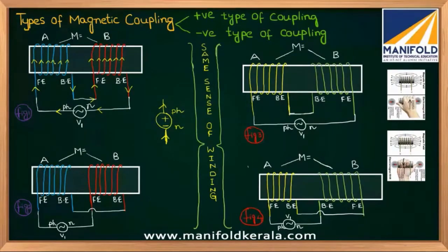Very good. This means in coil A, the direction of current from the front side is this. This arrow mark indicates, in coil A, the direction of current entering from the front end of the core, which you can see from the front side. The downward arrow marks are on the back side of your core, which you cannot see. Don't get confused by that. You can see the front side direction of current, which is upwards, in coil A and coil B.